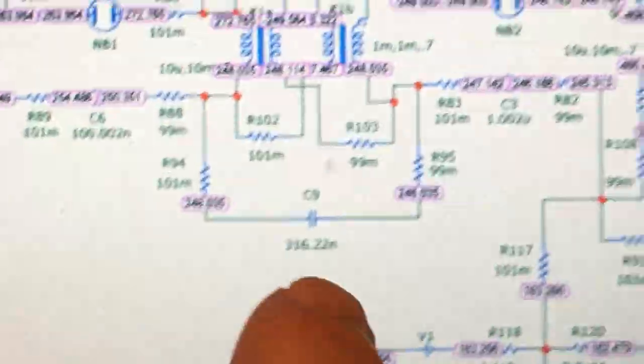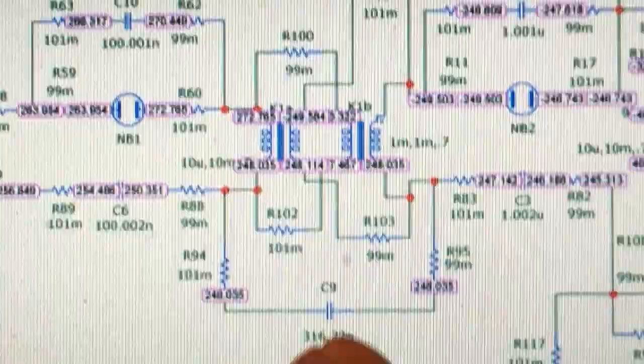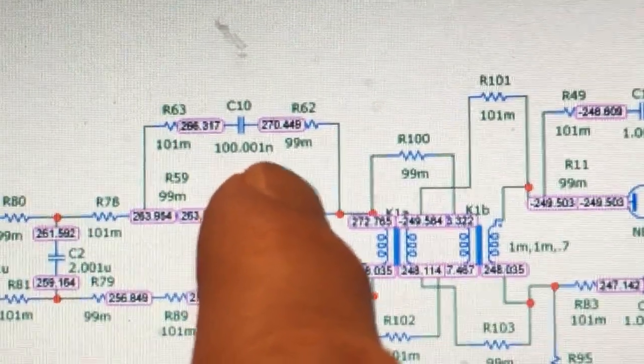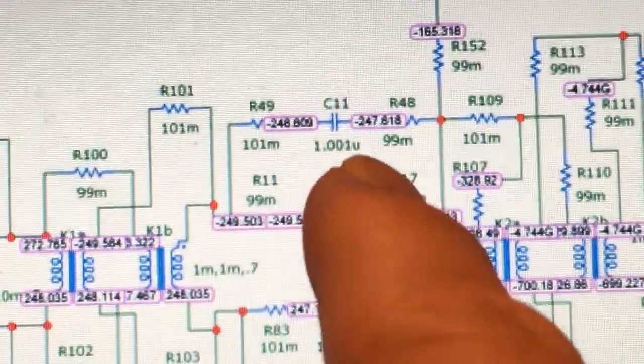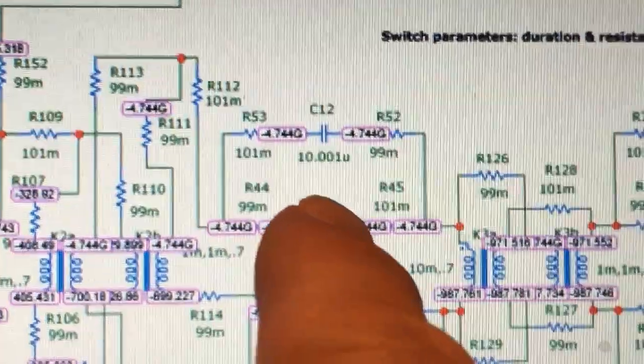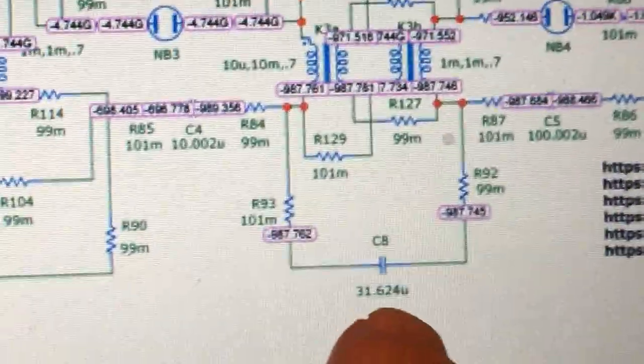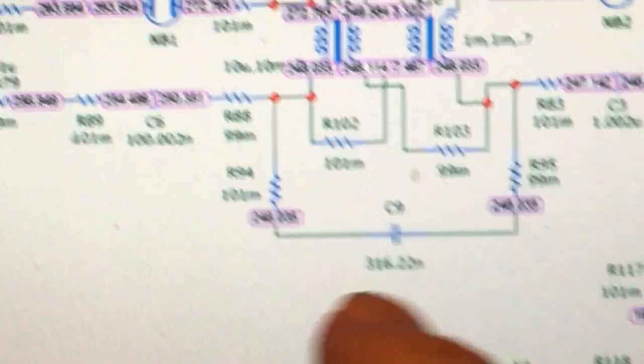between 2 modules. And I use the square root of 10 because the capacitance in this module is 100 nanofarads on each capacitor. Then the next one to the right is 10 times more, and so on, 10 times more and 10 times more. So the capacitor in between the modules, I use the square root of 10, and each one is 10 times more.